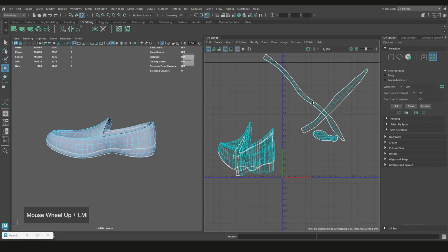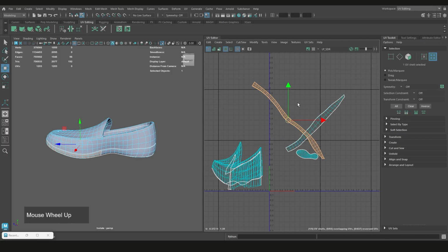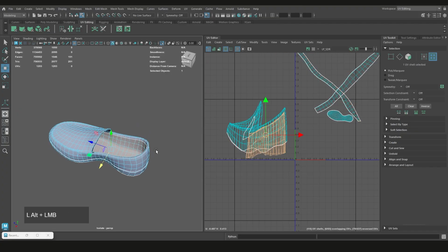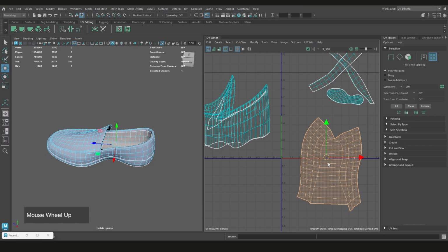And just a quick little heads up here, in Maya, if you shift click and drag, you can do this really slowly, or you can do it really quickly like that, and that will basically do the same. So it's the shortcut for doing this. So 1, 2, right, you just do this very quickly. You'll see people do that all the time with Maya, but because you guys don't know what the menus are doing, I can't really do that. It'll be a little too quick for you. So I'm going to do this piece, right, unfold, there we go, how quick was that? That's why I cut this piece here, just to give it a little bit of stretching.